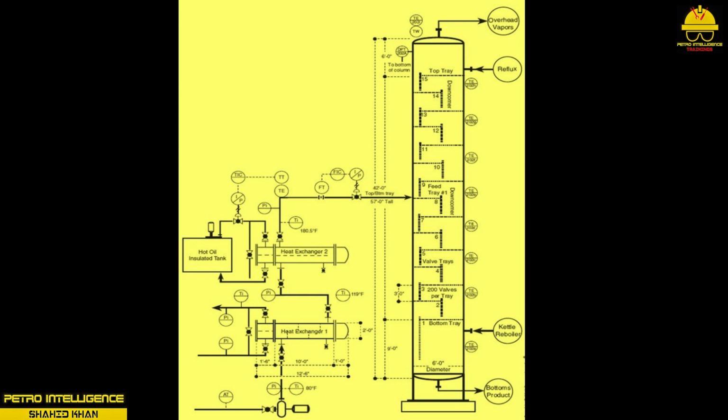To better understand how the principle of material balance works, let's consider the flow of raw materials through a column. Flow enters the column at 550 gallons per hour. This is roughly equal to 10 barrels per hour. Flow leaves the tower through one of three paths: bottom, side stream, or top.